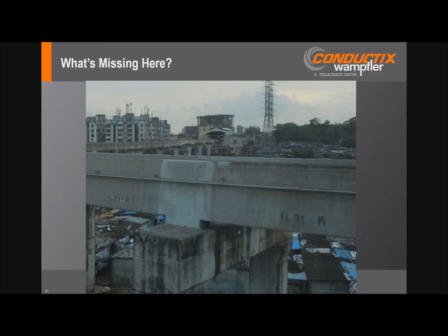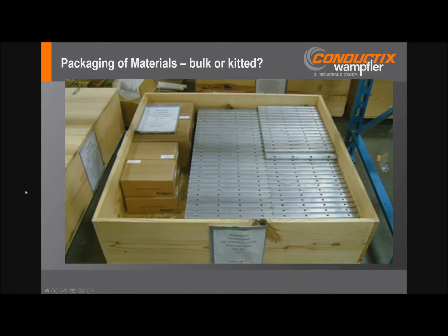Well, while it seems like a gross omission, as I mentioned earlier, the effect of this will probably be pretty minimal because the system design specification often includes a maximum allowed power rail deflection where a hanger is missing or damaged. So not ideal. Sometimes it's not easy to relocate those hangers. Ideally, what they could have done was cut the power rail and drilled it to relocate that. Sorry, I jumped ahead to the next slide here.